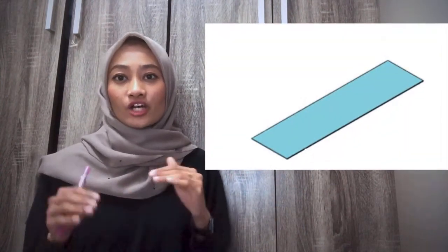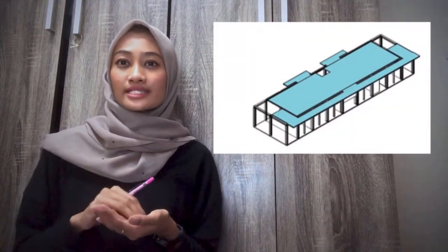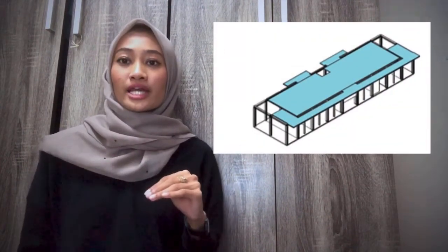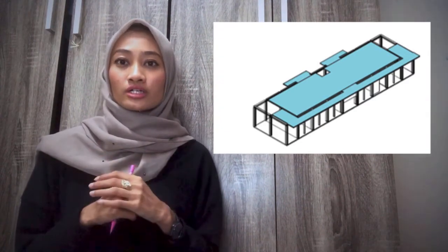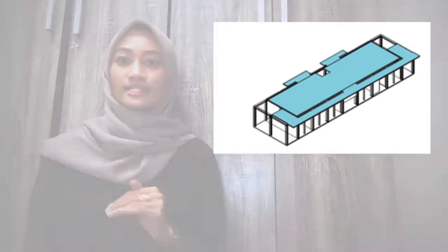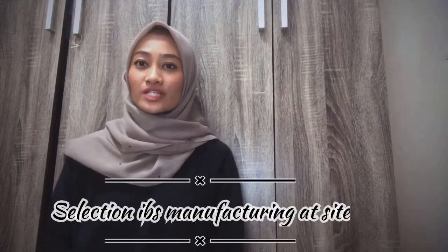After the installation of precast concrete beams, precast concrete floors are erected. Then the figure shows that secondary beams are constructed next to support the ground floor. After the ground floor, we move to the secondary beams. Then the first floor slabs are placed, mounted on the secondary beams, and the above steps are followed until the construction is finalized.